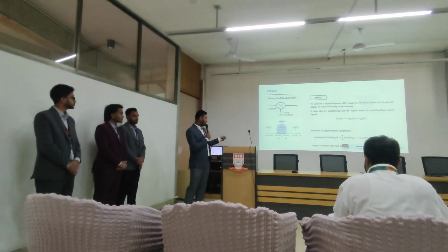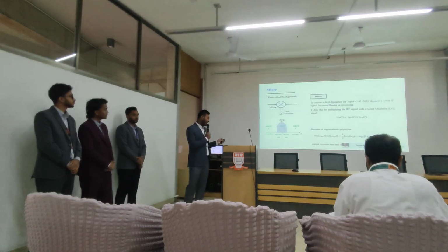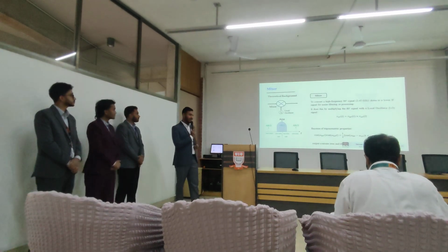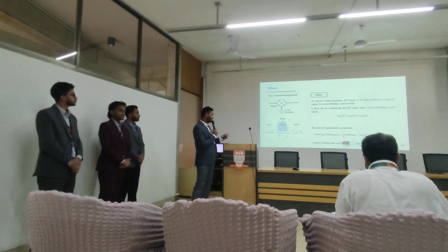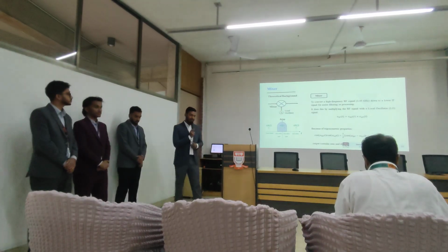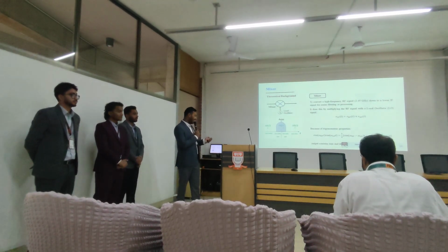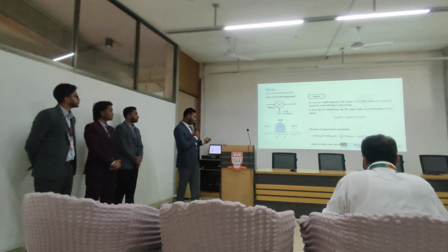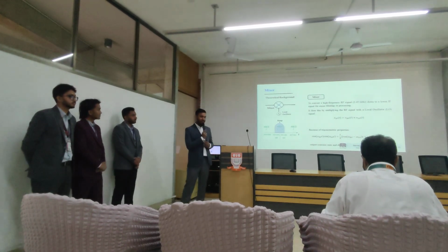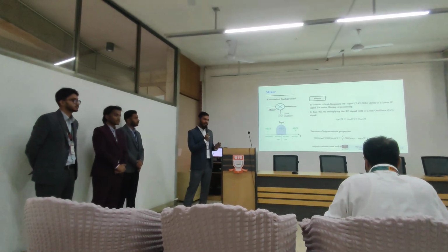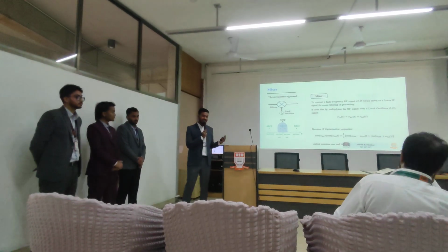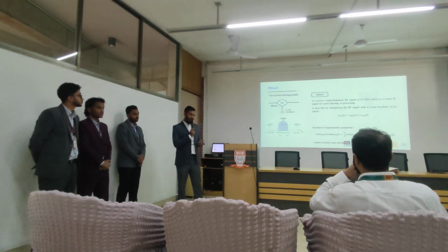As shown in the diagram, the mixer works by multiplying two frequencies: one is the RF input signal and the other is the local oscillator. This produces two new frequencies, the sum frequency and the difference frequency. In this case, we use the difference frequency, which is the IF signal that we want to capture.